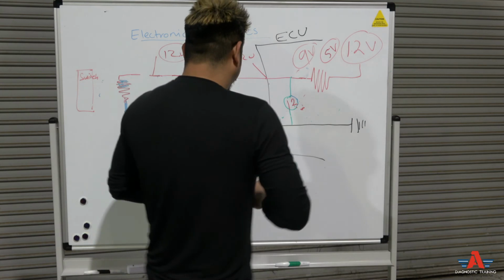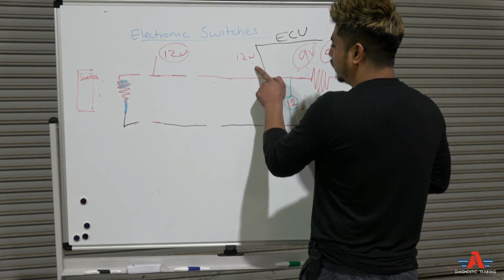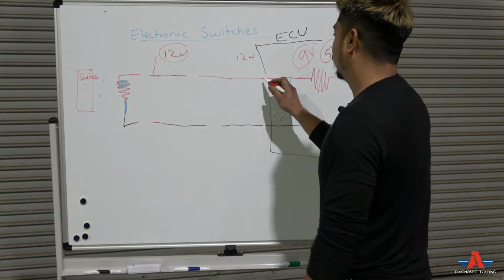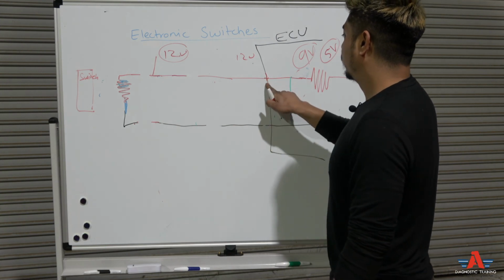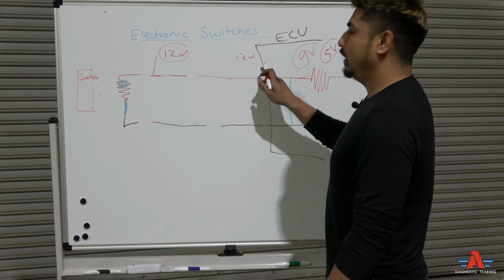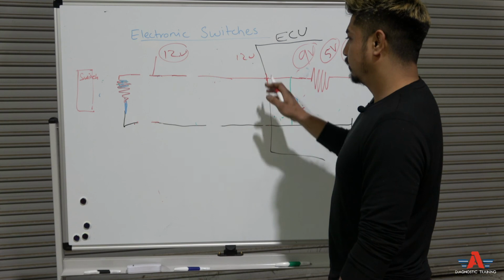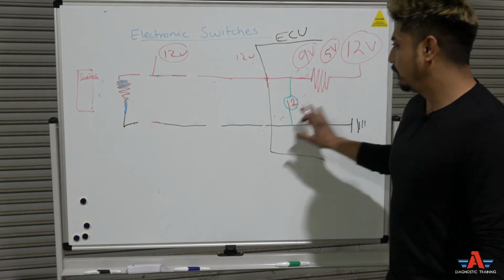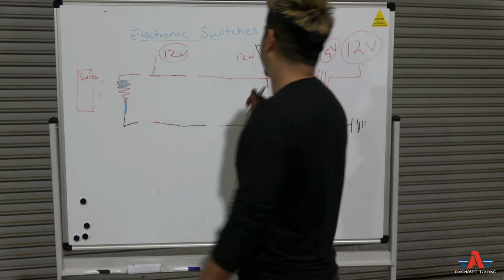If you see nothing, no 12 volt here, and it's not shorted to ground, means more than likely the problem is the computer itself, right?